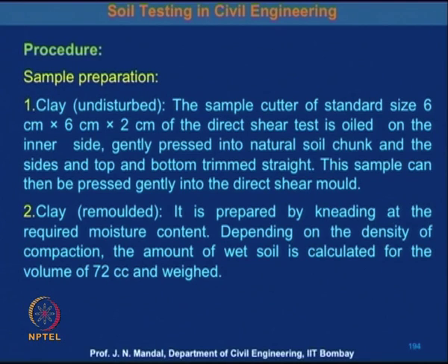If it is remoulded clay, it is prepared by kneading at the required moisture content depending on the density of compaction. So, how much you are compacting the soil sample?